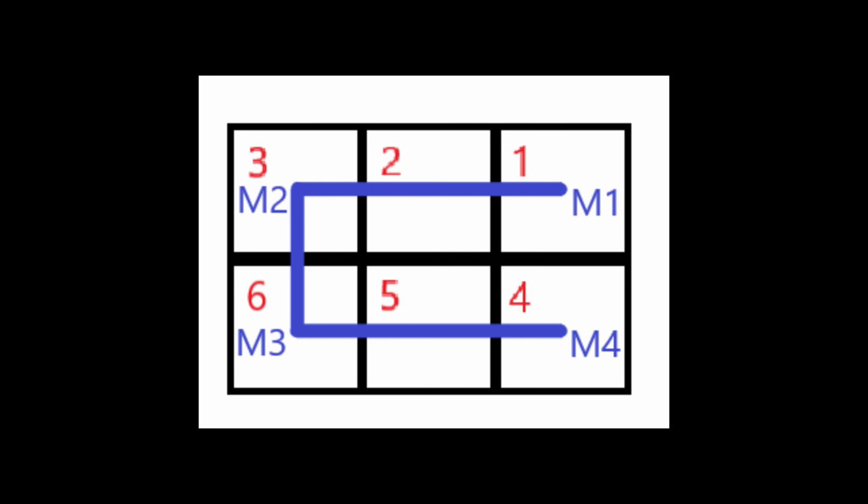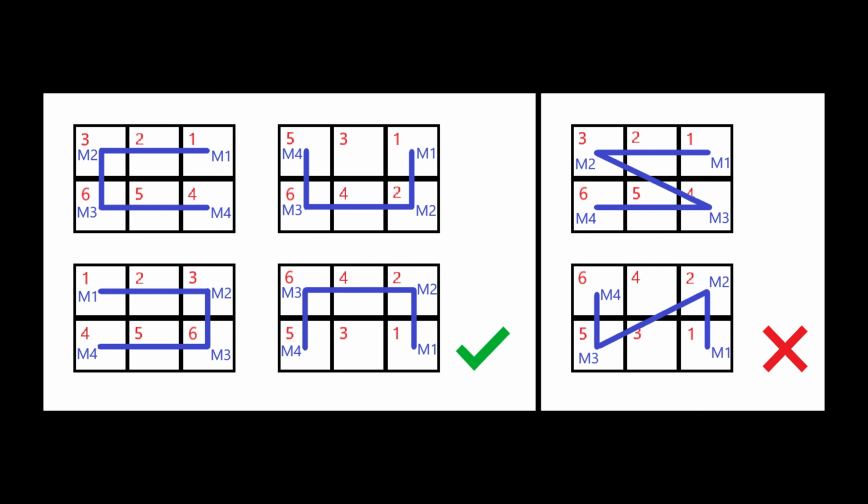The vertices need to be taught in the correct order. Vertex 1 will be the first object. Vertex 2 will be the last object on the first row. Vertex 3 will be the last object on the last row. Vertex 4 will be the first object on the last row. Simply put, the direction of the palletizing order does not matter, meaning the order of the vertices can be clockwise or counterclockwise. It cannot go via a diagonal path.